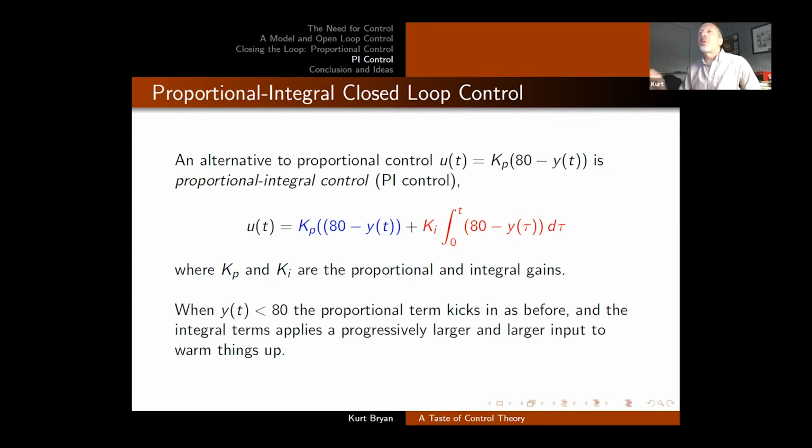The integral term will come on as well. As time goes forward, if the temperature remains too low, this integral term keeps winding up and cranking up the heater until the system stabilizes at some new value. The question is, what will it do?